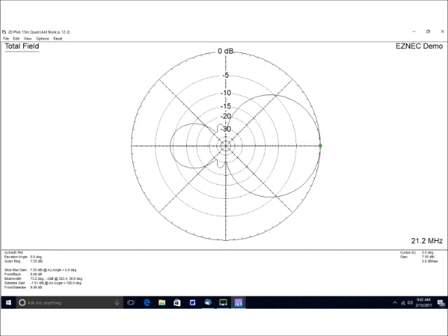Real tight, in a very specific direction. But again, it's done with this thing they call phasing. Yes, sir? So by changing the phase, you can change the angle of the lobe without that antenna having to turn. Right, because you turned it electrically. You don't have to turn it physically. There's a lot of ways of doing these things.